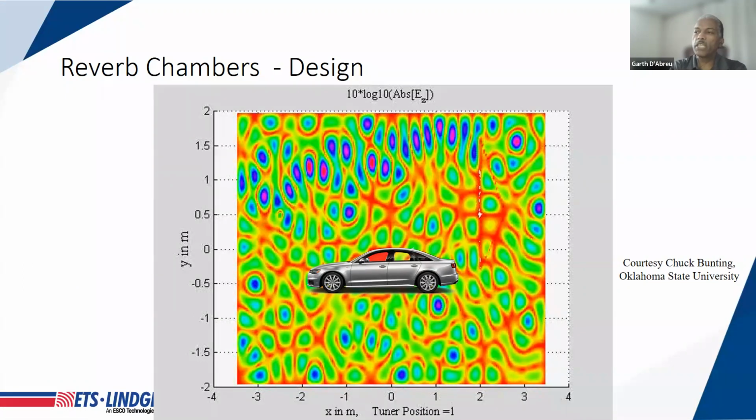There are some potential gotchas when doing tests in this type of environment. One of the obvious ones is with the speed at which you change the position of a particular hotspot relative to a particular component. And what that relates to is how you stir the modes, whether you rotate that tuner or shake the fabric tent continuously, or whether you have discrete positions of the reflecting structure that can hold a particular field pattern for some fixed duration of time. And obviously that has an impact in how the devices respond.